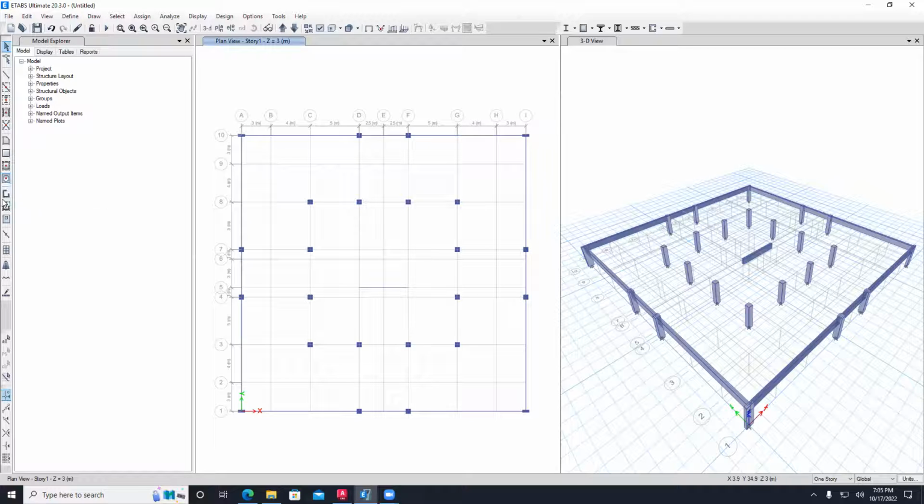That means this is how I can draw a wall section. If I put my cursor here, you'll find draw walls. But draw walls is only activated if your 2D window is activated. You cannot draw them on the 3D. So if I click on the 3D, they will be deactivated. So you will have to make sure that you are on the 2D screen and you hit draw walls.